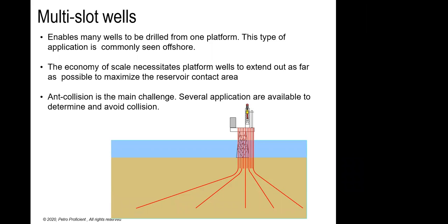This is also in the scope of directional drilling. A directional drilling professional needs to run some modeling and do anti-collision analysis and let the company know how close you would be getting to another well, which may be a producing well. And imagine if you drill into a producing well, it can be a disaster.